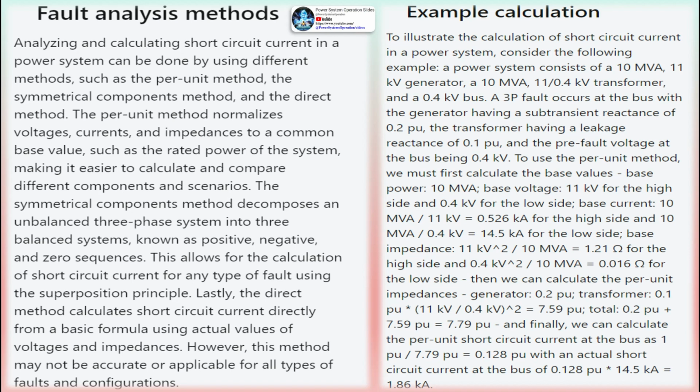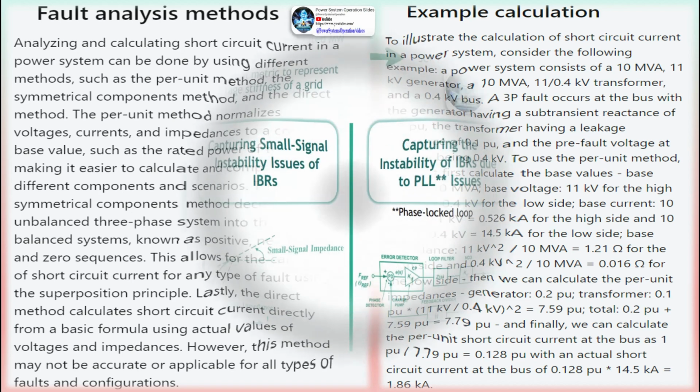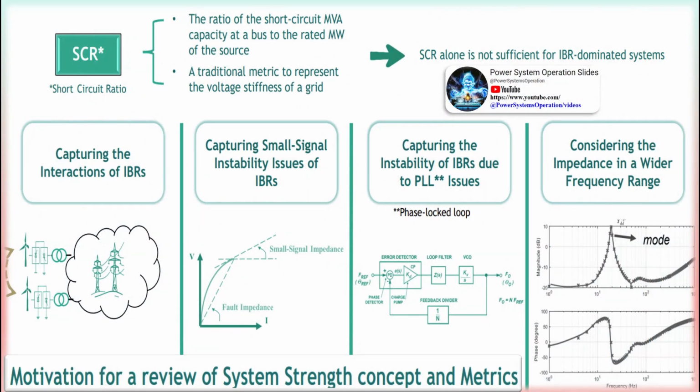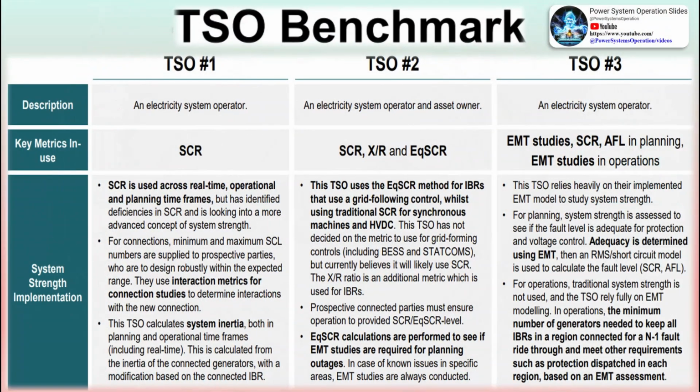Short-circuit calculation and study standards. The IEC 60909 International Standard series distinguishes 4 duty types resulting in 4 different calculated short-circuit fault currents: the initial short-circuit current Ik″, the peak short-circuit current Ip, the breaking short-circuit current Ib, and the steady-state fault current Ik. ANSI Standards, North American Standard. IEEE Standards covering short-circuit current fault calculations for low-voltage electrical systems below 1000 V are IEEE Standard 242-1986, IEEE Standard 241-1990, IEEE Standard C37.13-1990, IEEE Standard 141-1993. IEEE standards dealing with short-circuit current calculations for medium and high-voltage electrical networks could be seen in the table.